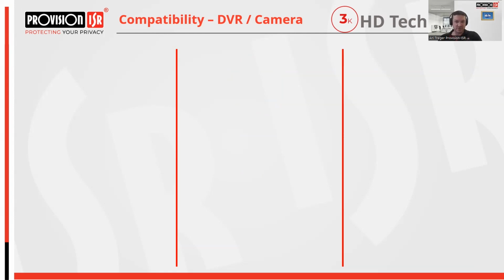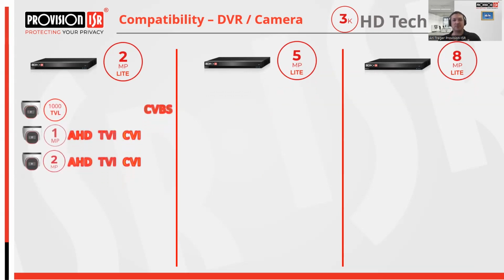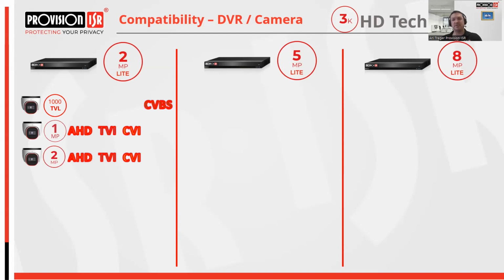The DVR resolutions that we do offer are 2 megapixel, 5 megapixel, and 8 megapixel, meaning that the DVR supports up to its respective resolution as the maximum. Naturally, they are compatible with cameras of equal or lower resolutions, and here's a breakdown of their compatibility. 2 megapixel DVRs are compatible with 2 megapixel, 1 megapixel cameras, as well as CVBS, which translates to 1,000 TV lines.